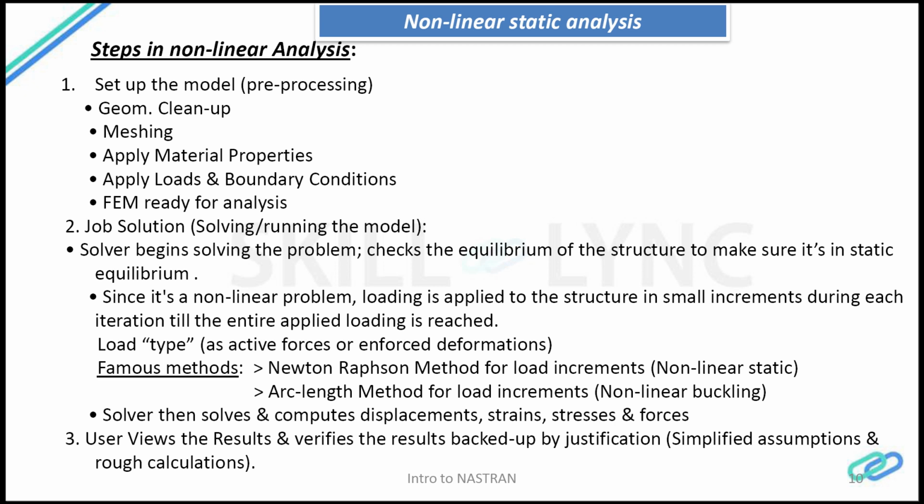Finally, once the nonlinear solution is converged or solved, it is the duty of the user to make sure that the results make sense and are valid, by using simplified assumptions and simplified rough calculations. You should be able to check and verify that the results are correct. So that's the fundamental difference between linear and nonlinear static analysis, where in nonlinear static analysis the load increment is done in steps.